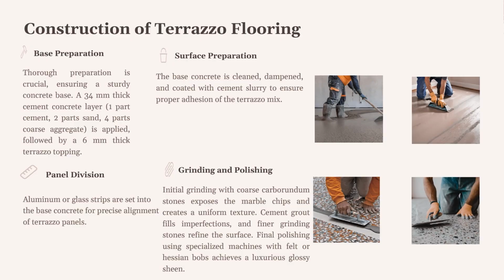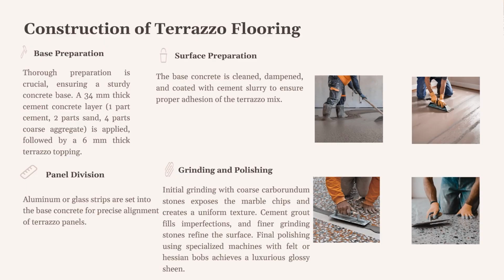Once the terrazzo mix sets, the surface goes through a grinding process using coarse carborundum stones to expose the marble chips and achieve a uniform texture. This is followed by cleaning and filling any imperfection with a cement grout to ensure a smooth finish. The grinding process continues with finer stone to refine the surface even more, creating a polished look. Finally, the floor undergoes a thorough cleaning and polishing with special machines fitted with felt or resin bobs, leaving it with a luxurious glossy sheen.